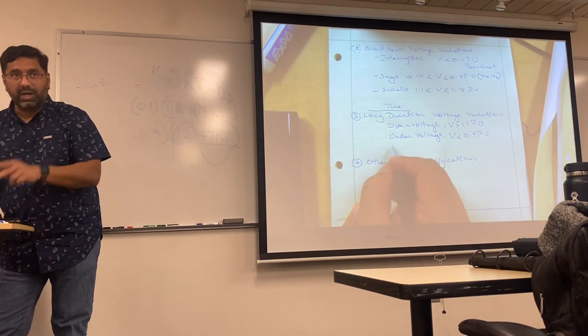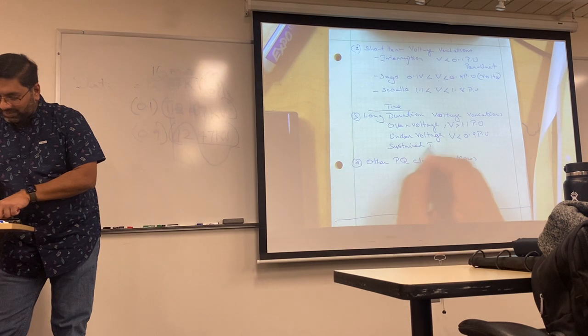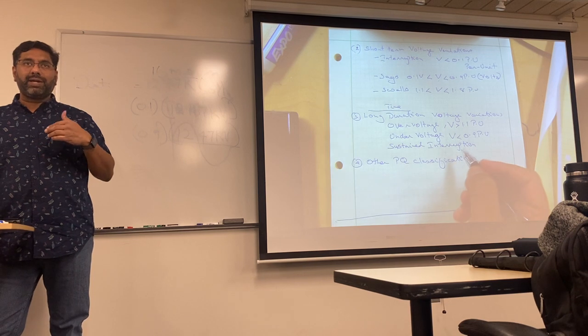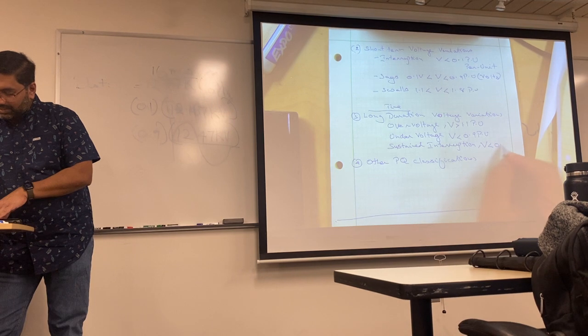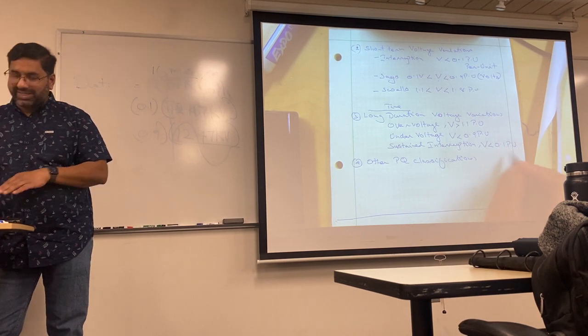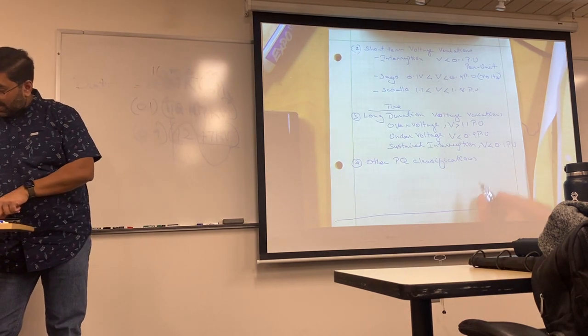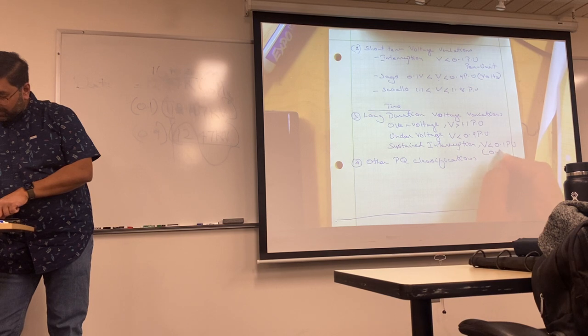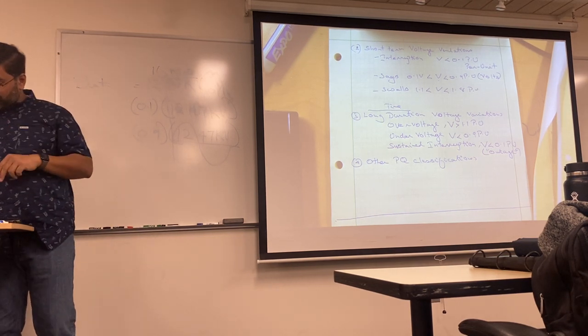And then you have, I think it's Danny who asked me, a sustained interruption. This is when we tried opening and closing our breaker at the end, we tried rebooting our system, nothing works. I'm still getting a voltage which is less than 0.1 per unit, which means that there is a dead bird, an animal, a branch that needs to be physically removed. And this is what we call an outage. It's the last thing that we want to do, but when nothing works, then we just take an outage.